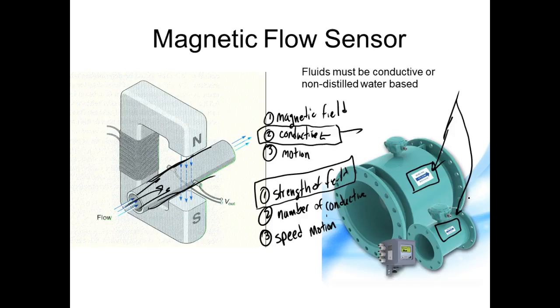So these guys here come in varying sizes. The thickness of the wall determines how much pressure it can hold in, right? And then the inside diameter determines how much resistance it would have for a certain amount of flow. These guys here would handle a lot of flow, right? But what you're going to choose is the one that is as small as you can possibly get and still meet the demands that you have.